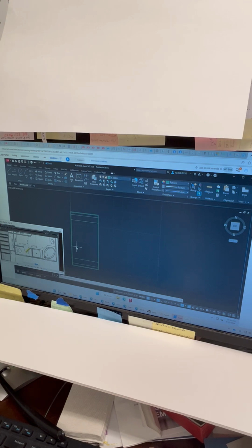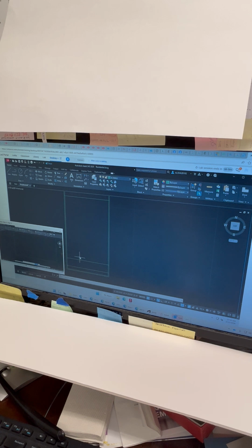All right, now that you've seen that, focus in on the lower left-hand corner. I'm going to start with the vertical elements first. So I want you to start the offset command. The only dimension that repeats out of all of this is the 3.5 inch wall thickness.